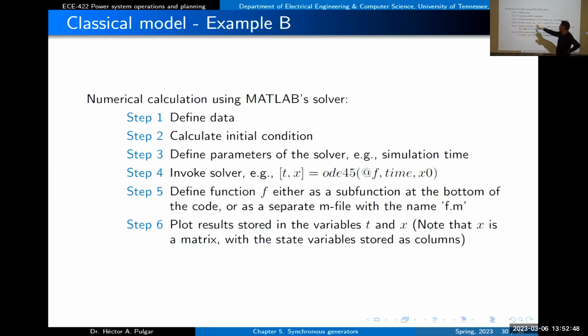Step 4, we invoke the solver, and that is the typical ode45. We can use different types of solvers. And in particular, later, we're going to deal with differential algebraic models. So in that case, this solver will not work. So we need to use ode23t or ode15s. But we will talk about that. There are different solvers we can pick from Matlab.